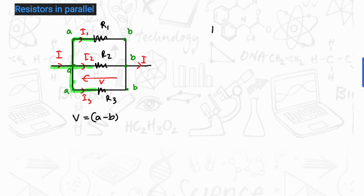Then we can say that I is equal to I1 plus I2 plus I3. In order for 2 resistors to be parallel, the voltage values at their terminals should be equal. Now in this case, we have A and B as the voltage terminals in all 3 resistors.